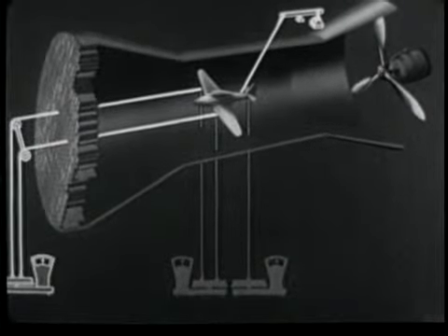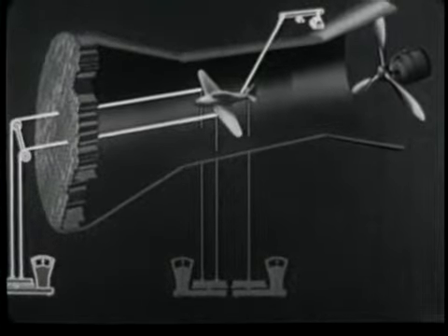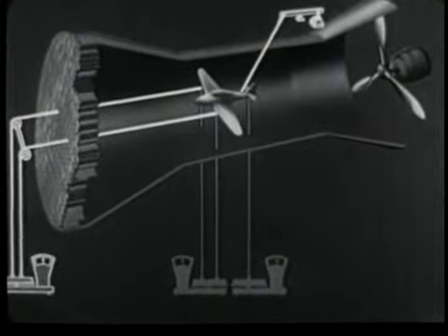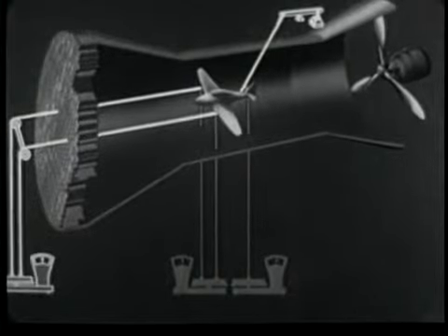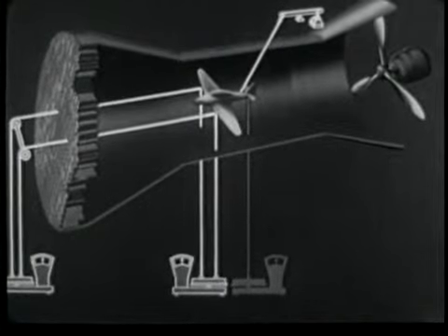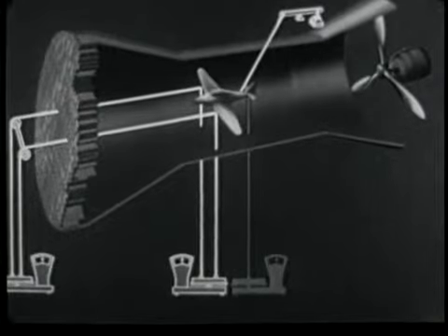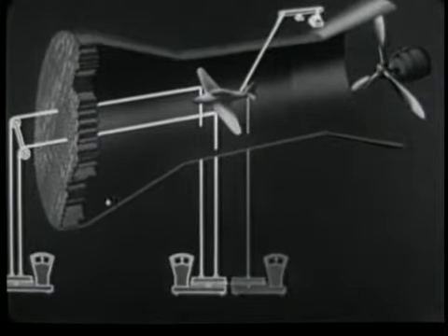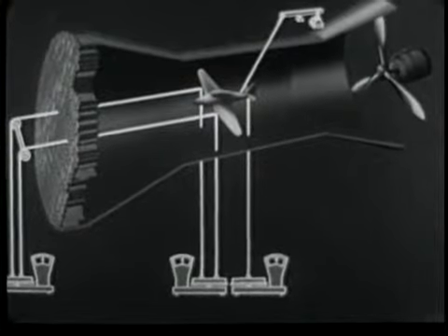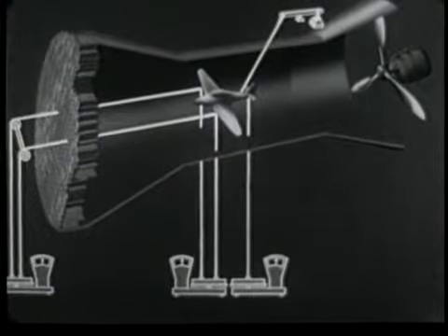From the leading edge of each wing, a wire runs forward in the direction of flight over pulleys, and down to a bar on a platform type of scale. A second pair of wires runs vertically downward from the wings to another scale. Finally, a wire extends from the tail down to a third scale. In this way, the model is suspended so that the various forces exerted upon it may be measured.